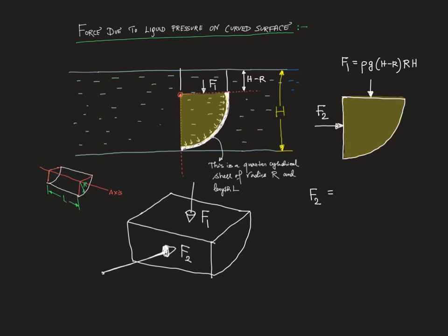see, just now we have solved all these problems, right? Force on a vertical surface is pressure at the centroid times area. So that's a rectangular surface. Pressure at the centroid means from the top, the height is how much? H minus R by 2, right? So F2 is rho G, because the total height is H, this is the midpoint, so R by 2 from the bottom.